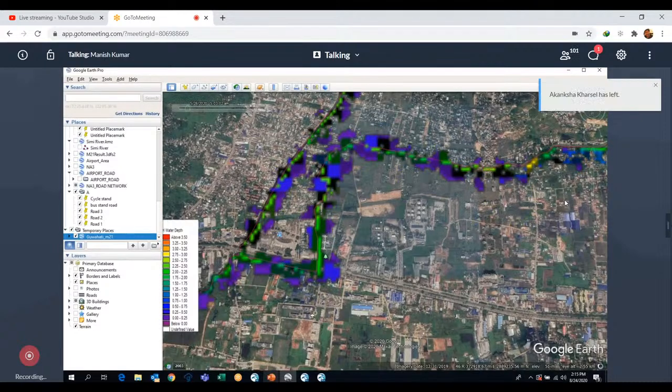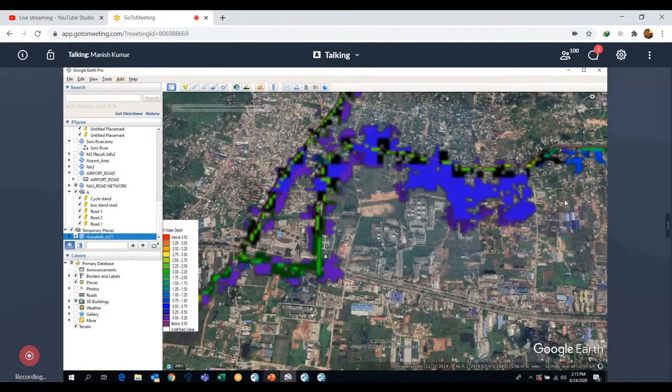They provide quantitative precipitation forecast grid-wise for your area, and then you use it to get forecasted runoff in your river sections. Once you have this forecasted runoff, you can see along the river how much area will get inundated and which area will get inundated.